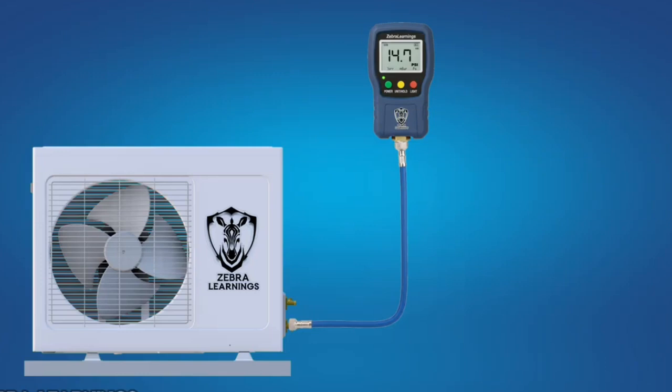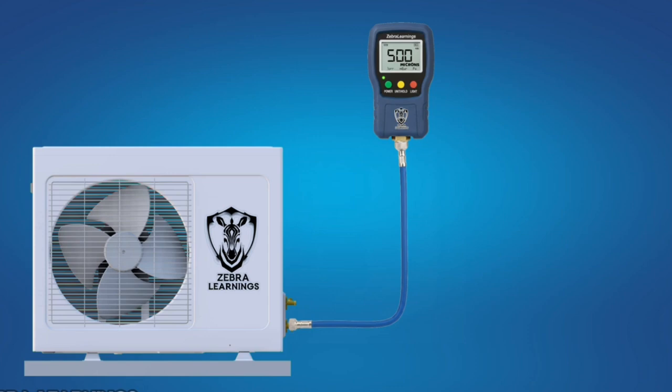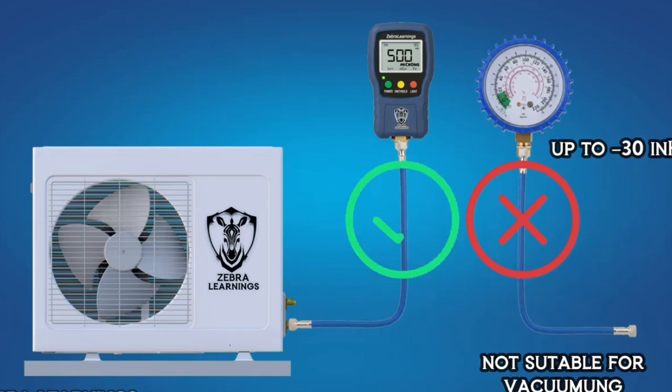In HVAC, we usually pull the vacuum down to about 500 microns, which is equal to 0.0097 psia. Because vacuuming needs us to measure a pressure lower than the atmosphere, we must use an instrument that measures absolute pressure, not gauge pressure. That's why the manifold gauge is not suitable for vacuuming. It can show only rough vacuum values up to minus 30 inches of mercury, but to know the exact deep vacuum, we must use a Micron gauge.